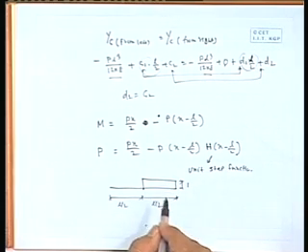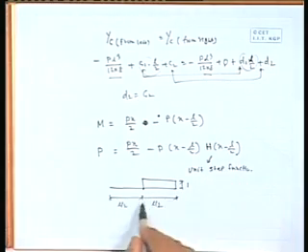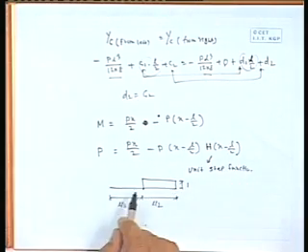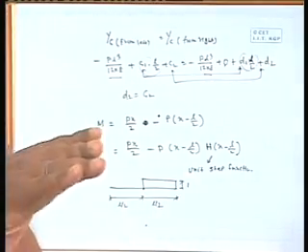That is the reason, very simple. The function is 0 when it is less than L by 2. So, when it is beyond the load, it is 0. When it is beyond the load means it is before the load. When it is after the load, the value is 1. So, here also when it is before the load, only this term.